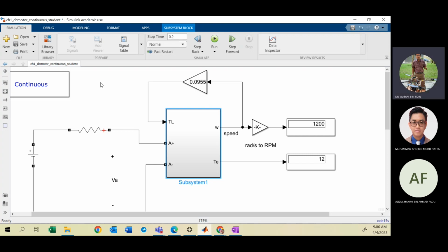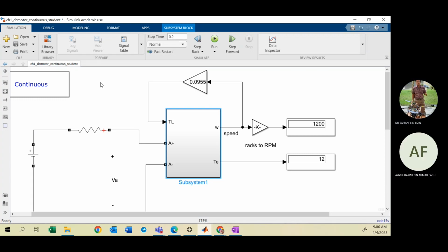Try to verify. Based on the calculation values that we have discussed just now, you can substitute the values, for example, the value of VDC, rheostat resistance, the duty ratio. Then you verify. Can the motor obtain the desired speed, 1,200 RPM?